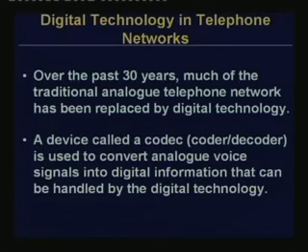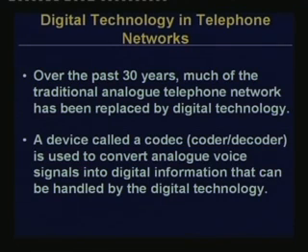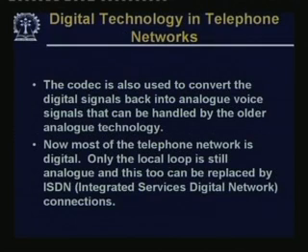Now, just quickly on the digital technology in the telephone networks. As mentioned earlier, traditionally everything was analog, then the exchanges started getting converted to the digital technology. So, what you do, a device called a codec, as I mentioned, is used to convert analog voice signals into digital information that can be handled by digital technology. The codec is also used to convert the digital signals back into analog on the other side, so that voice signals can be handled by the older analog technology.